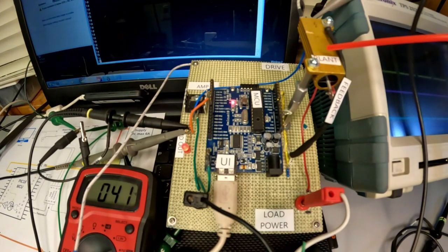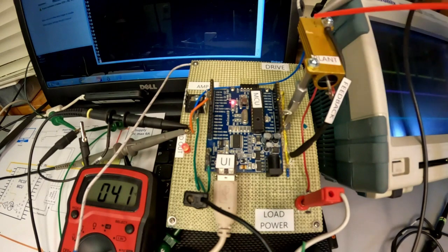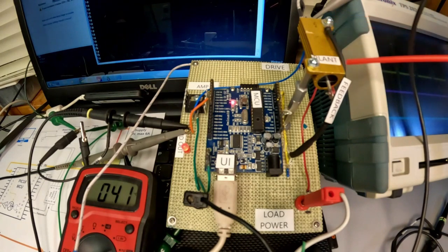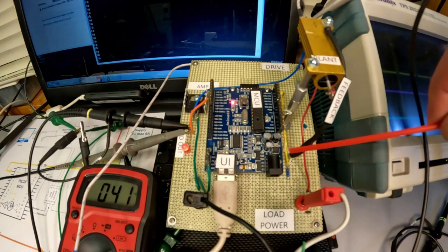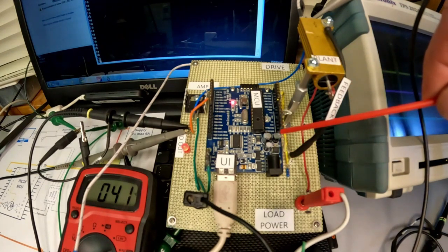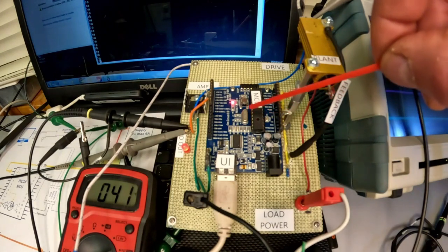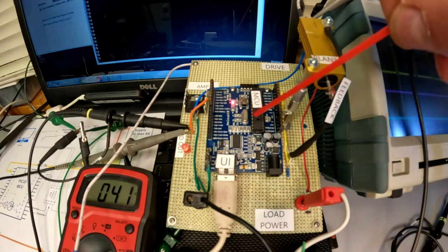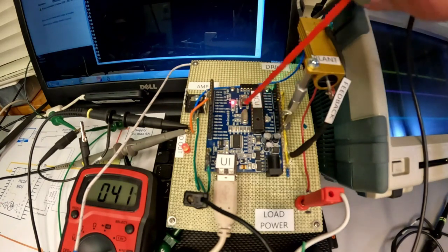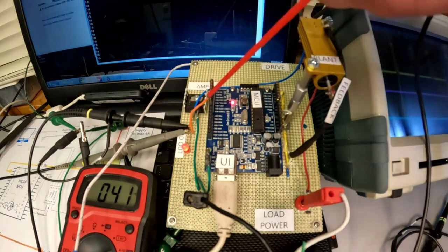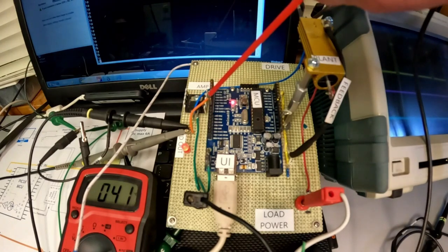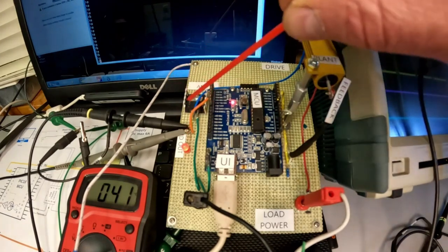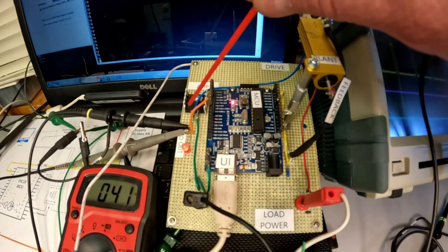That is the device that we are controlling or regulating the surface temperature of, according to a set point. The feedback point is a thermistor, a negative temperature coefficient thermistor, which we can go into more detail on later. That's providing feedback to an analog to digital converter input, which is sampled by our microcontroller, applies logic and a gain, and proceeds to output or modulate the duty cycle of a PWM signal, pulse width modulated signal, and we'll get into that. What that does is it switches what we call a low side switch, a power transistor.